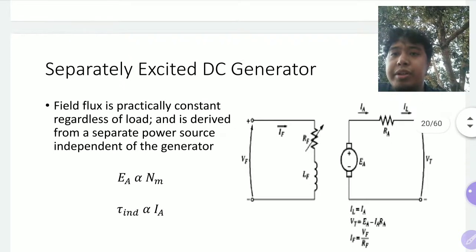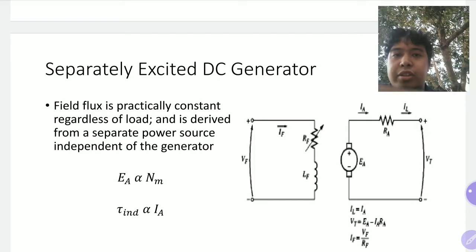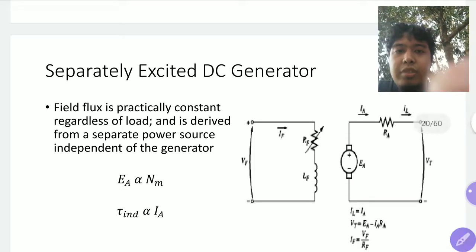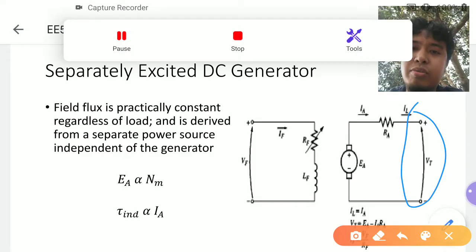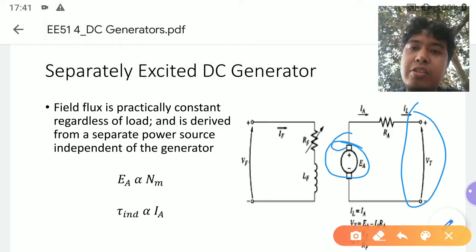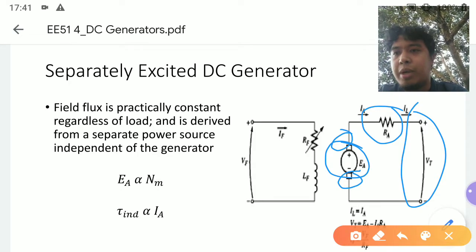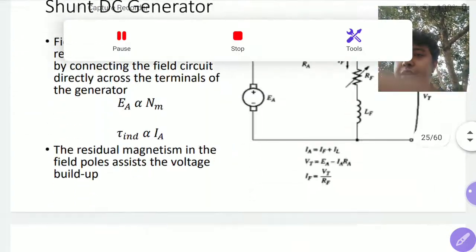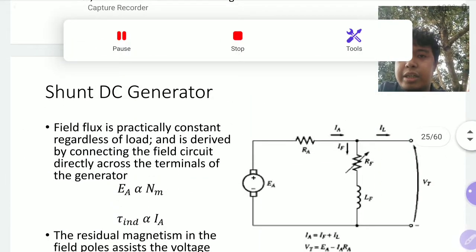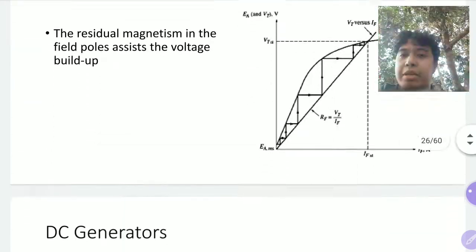because that may differ according to the connection of your generator. For example, for separately excited generators, the voltage at the terminal is equal to the induced voltage, less the voltage at the brushes, less your voltage drop due to copper losses. For shunt generators, you have the same formula for terminal voltage.